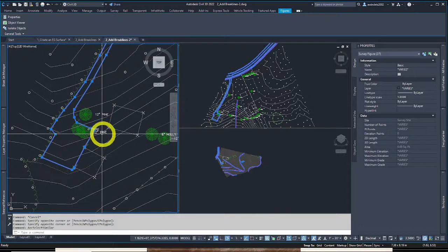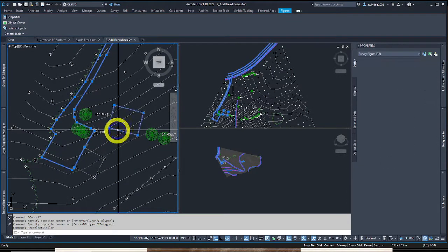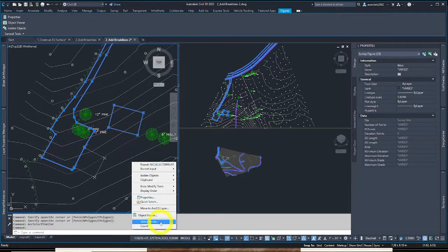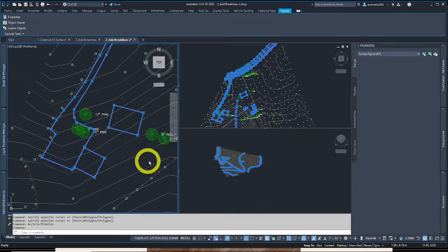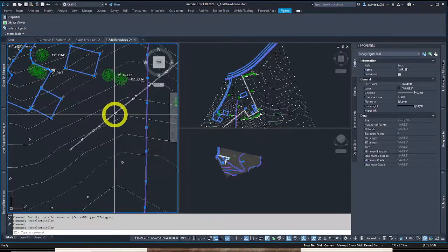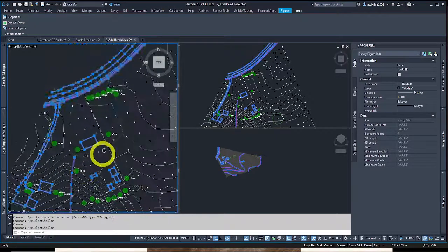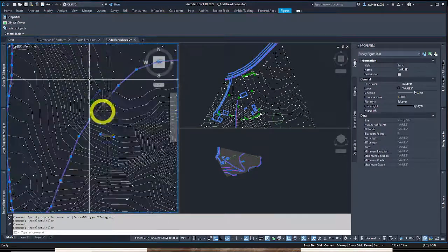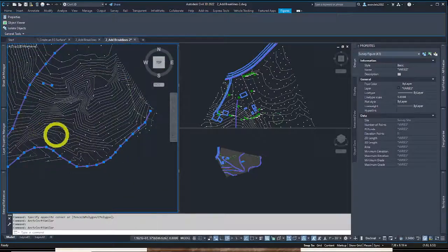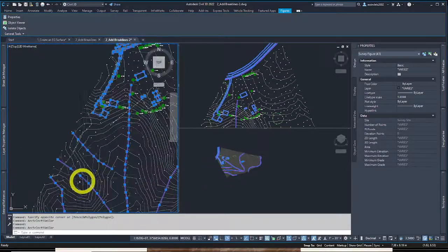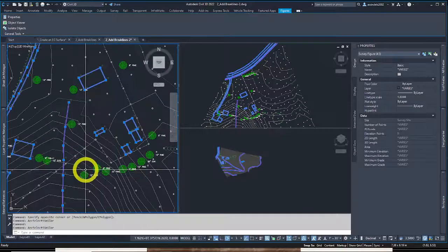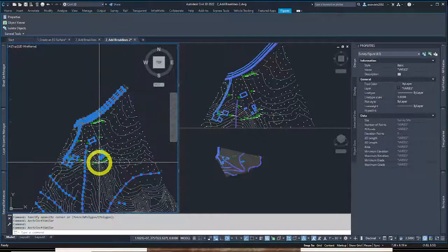These are not. Okay? These buildings are. These fences are not. So this is where a little bit of intuition is needed. Now, it didn't just do it automatically for us, like it said break lines yes and no in the survey database. This needs a little discretion. So I didn't select the ones that won't be in the surface, like the fence and the tree lines.